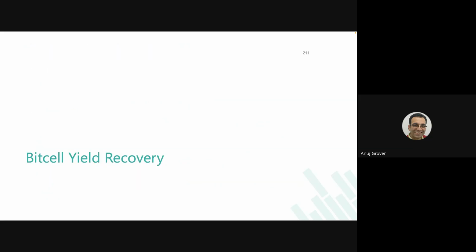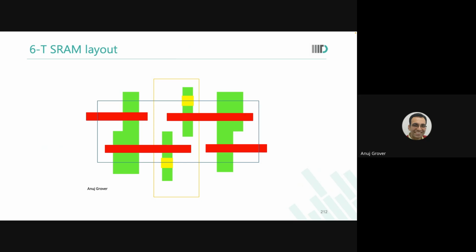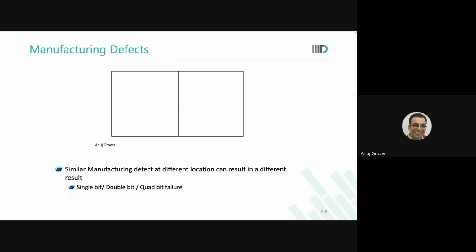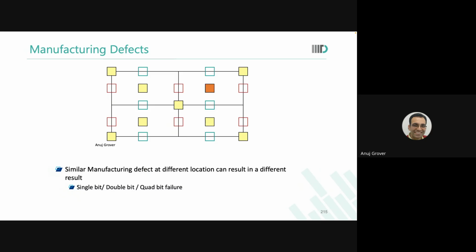So, see, we have always said that memory cell layouts are very, very dense. We have said that we will do a lot of sharing of devices, structures, contacts, vias, everything across the memory cell boundary. So that when we talk of an array, there are many structures of which some are at one boundary or another.